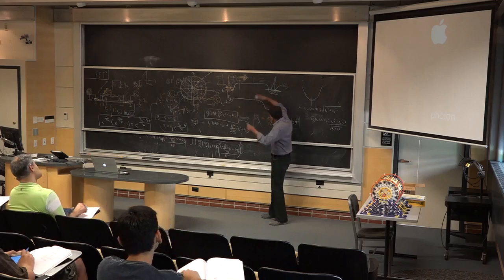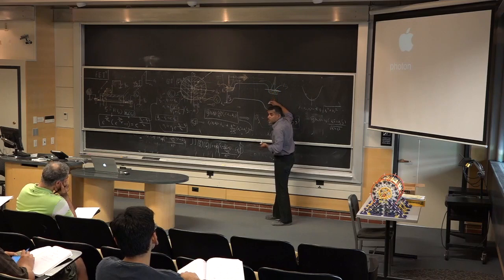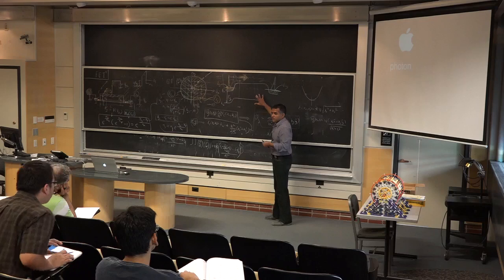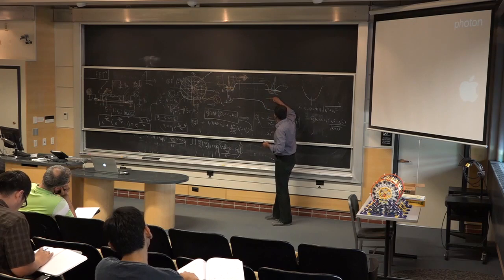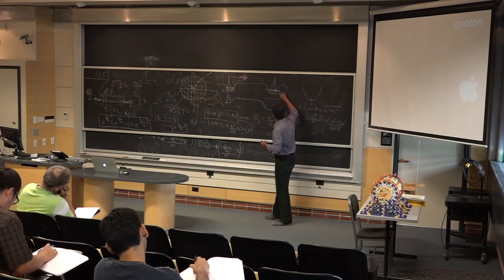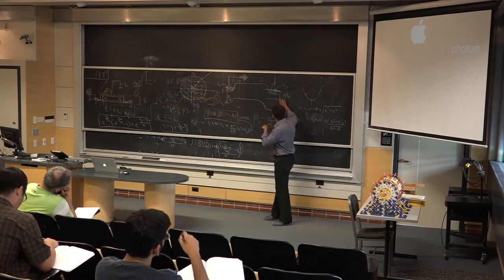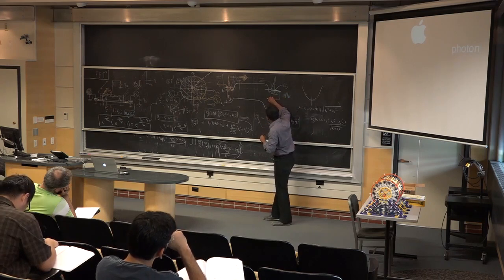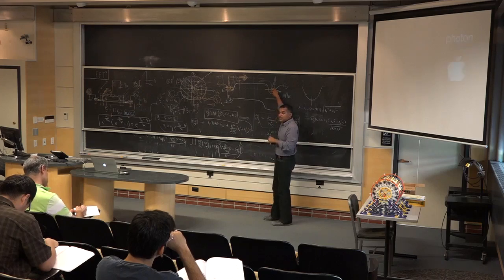Right? So how much will be the difference? Let's say I apply a positive drain voltage, then I'm going to actually push it down. Now the way to look at it intuitively is you're taking electrons away, in some sense. So you're going to push it down, and let's say the Fermi level of the drain goes here. So this is q times V drain source voltage. When the Fermi level has moved down here, this region is still heavily doped n-type. It has to remain charge neutral. It cannot just lose electrons.